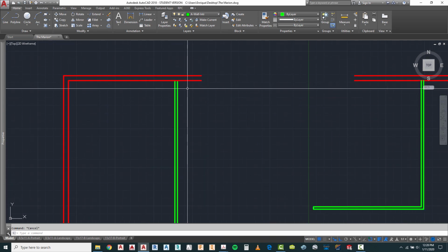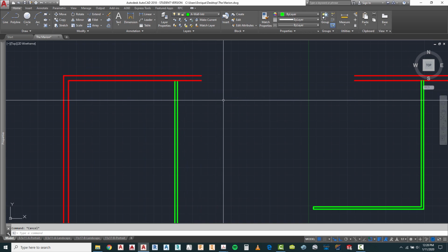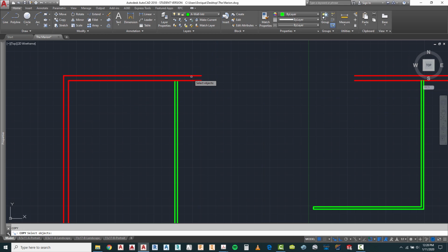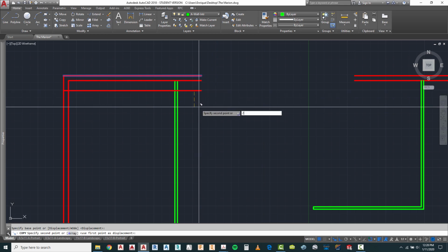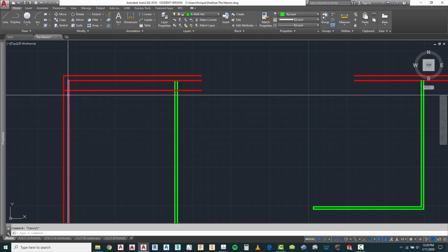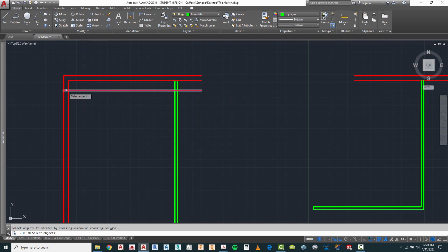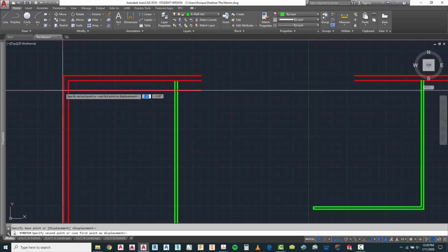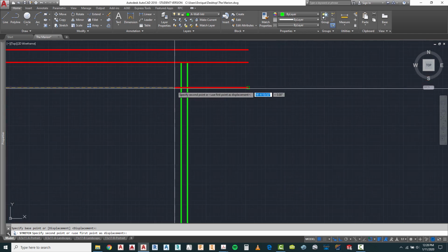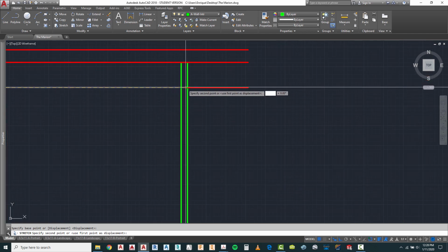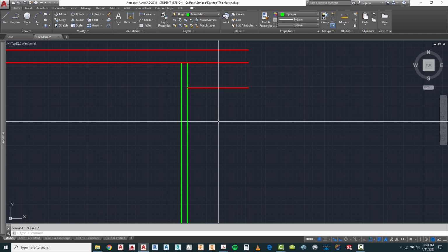Well, we have an exterior wall that's going to be 2 feet further down in here. So I can copy this guy and come down 2 feet. And I'm going to use my stretch crossing command right here and bring that all the way to this location here.